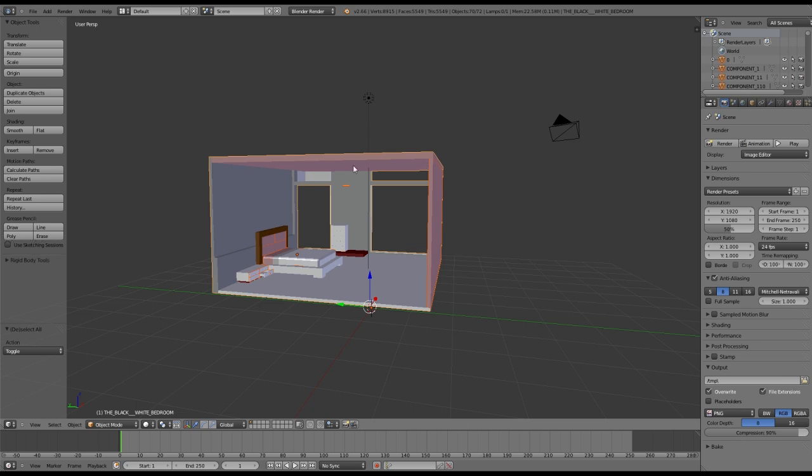This is actually quite tricky. This can sometimes mess things up. So just so everyone knows, I'll be covering this in the tutorial in a more intuitive way. But when you have everything selected, so I'll do that quickly, you want to make sure one part of the mesh is specifically selected, because at the moment there is no parent object selected. So what I want to do is hold down shift and simply select with my right mouse button on one of the objects in the scene.